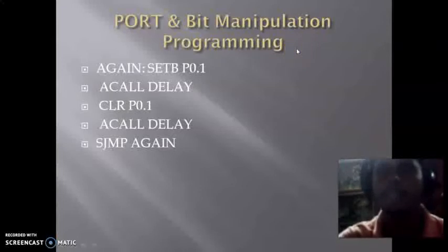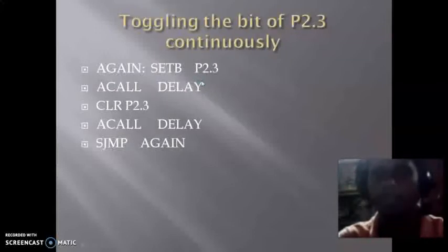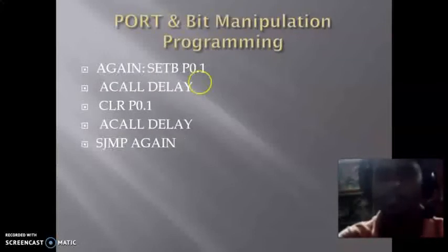Next, SETB P0.1, and we clear the particular bit P0.1 like the previous one, P2.3. Any pin of any port can be set as well as reset.